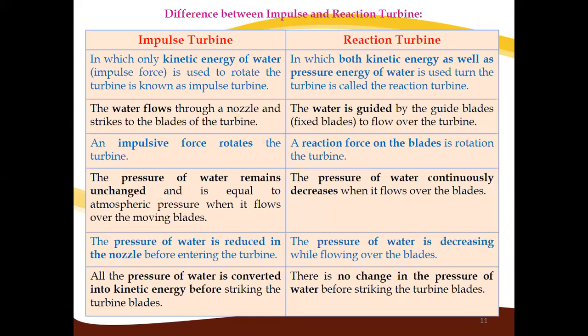Now, in the exam, mostly a question will be asked on the difference between impulse turbine and reaction turbine. So we'll see this difference. In an impulse turbine, only the kinetic energy of water, that is the impulse force, is used to rotate the turbine. In a reaction turbine, both the kinetic energy as well as the pressure energy of water is used to turn the turbine. So both an impulsive force as well as a reaction force are there, by which it will run the turbine.